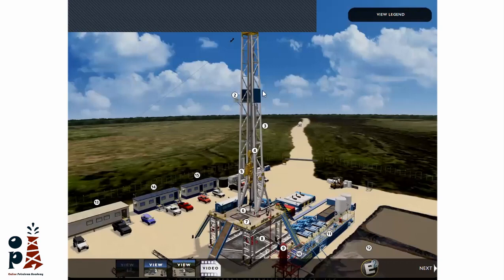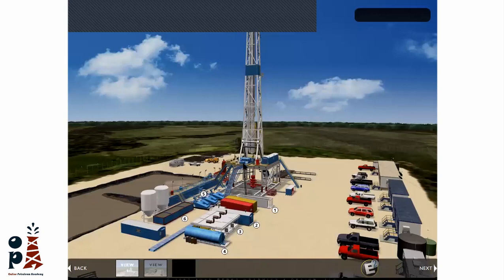When the stand goes up with the top drive, he pulls the stand and puts it in the fingers of this board to rack back the stand. Also, you will find here, this number 7 is the mouse hole. The mouse hole will be clearer in another view. Okay, this is the mouse hole.